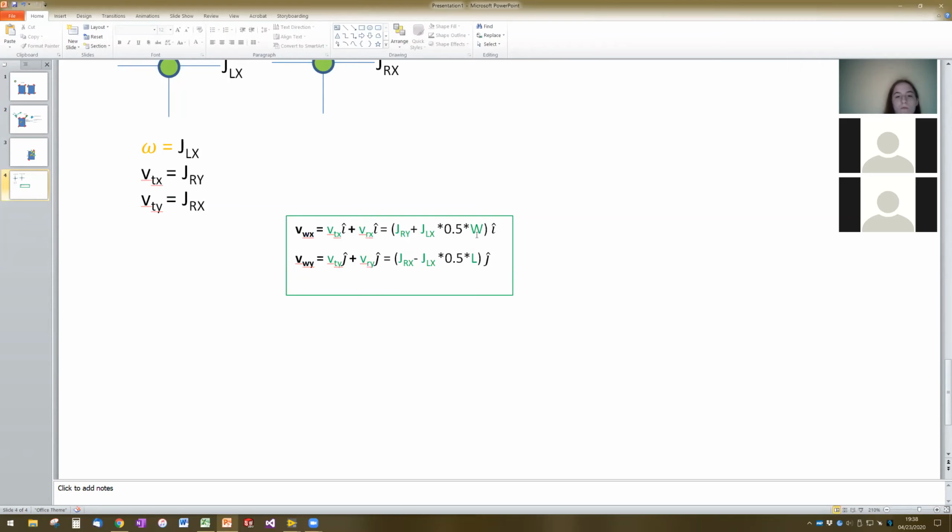There may also be, I have to spend some more time to look at this, for a square robot where L and W equal each other, that's all that would change. In a rectangular robot or in a more complicated configuration like a 3-wheel swerve, you would also have to deal with some changes in the distances that are here. But in our case, L and W are the same for our robot because we have a square base. Do those sign differences as we look at the different wheel modules make sense? Or are there any questions?